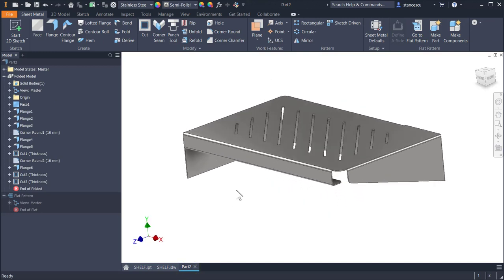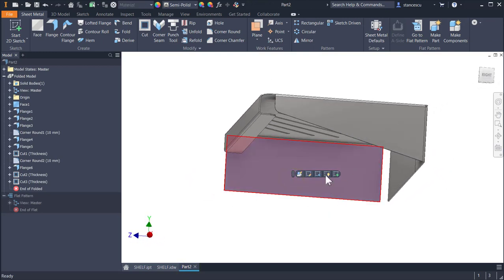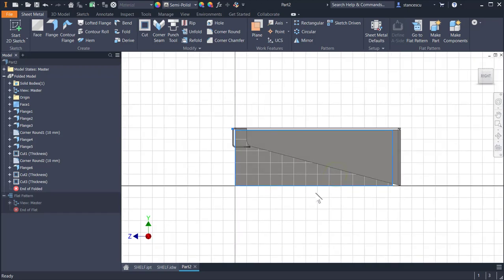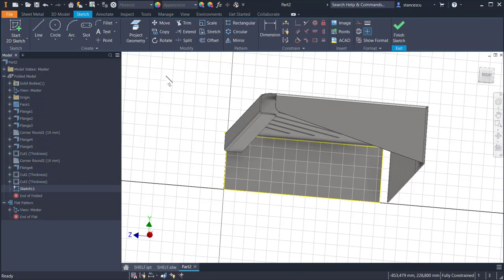We go to this face, we select the sketch, I apply F5 to have the same view, I place 2 points, 1, 2, I ask for them to be on the same horizontal, I place the dimension of 40, the dimension of 50, which is here, and 170.